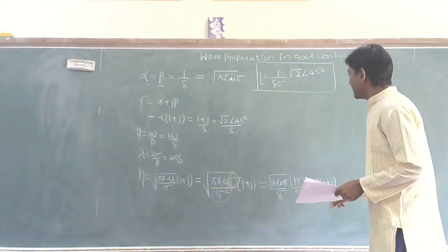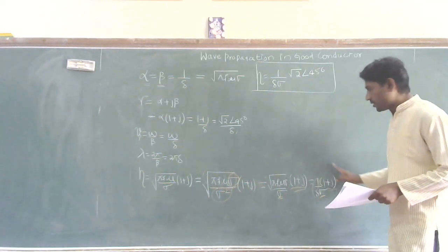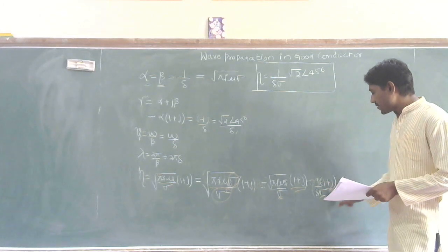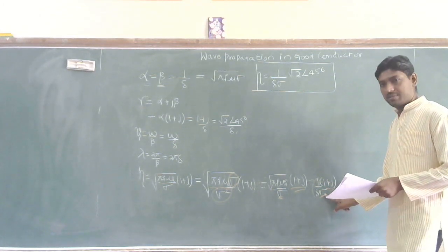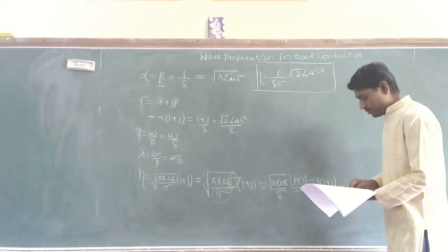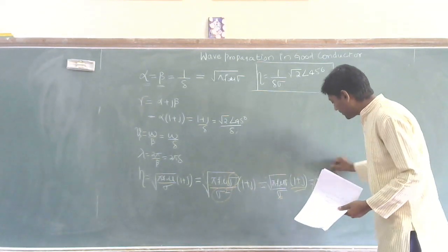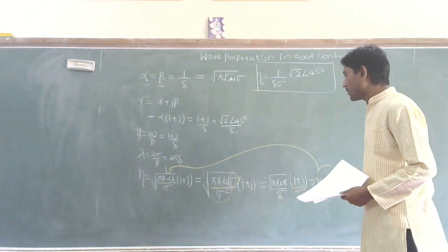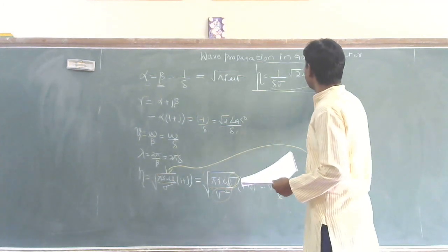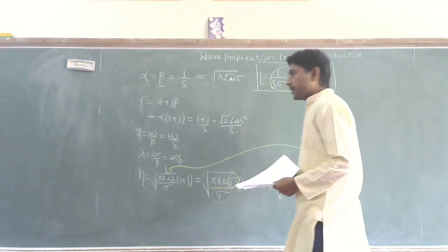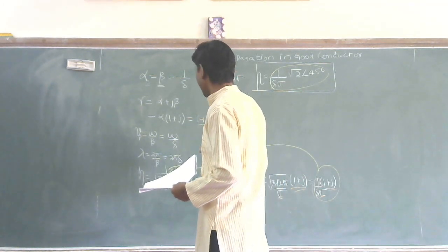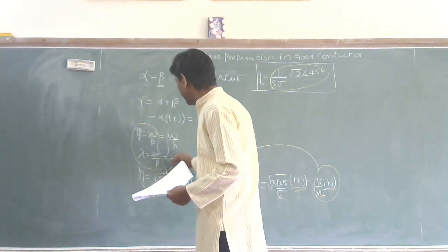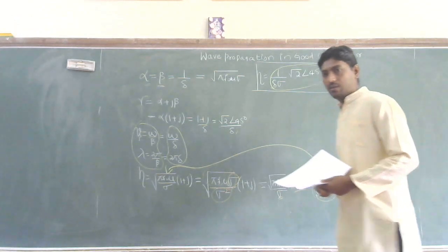So you could really check that the intrinsic impedance for a good conductor is (1 plus j) by skin depth times sigma. What I mean to say is, remembering this formula is quite easy as compared to remembering this one. Or you can remember this one. It is really the same. Anyway, these two are quite simple to remember. Or even you can really remember this one.